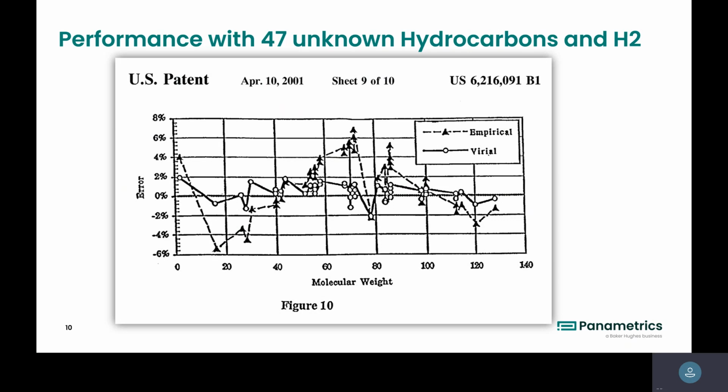And our method has shown that for gases ranging from pretty much hydrogen all the way up to molecular weight 120, that's C6 or C8, even above C6 or C8, in the whole range the error is within 2%. It's actually 1.8% on average when calculating molecular weight from sound speed. You can get very accurate results.